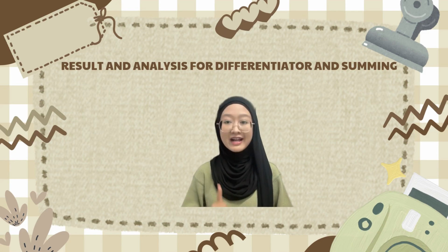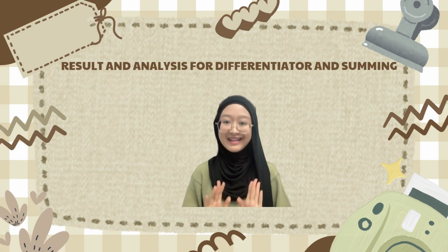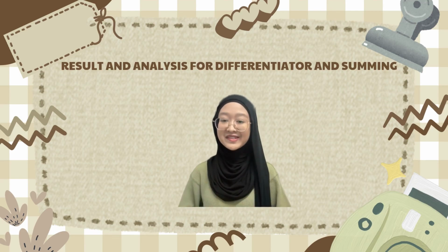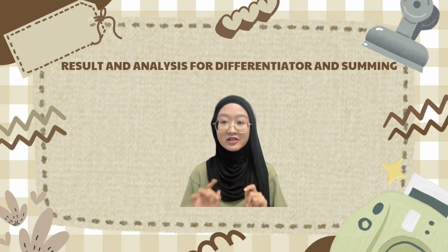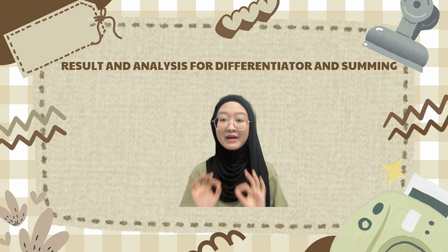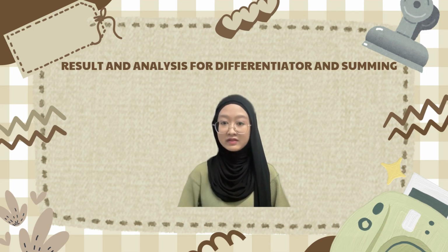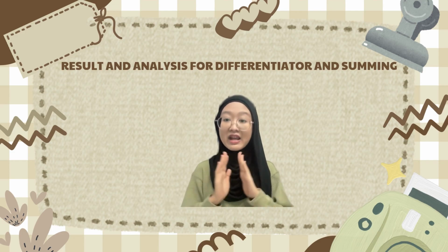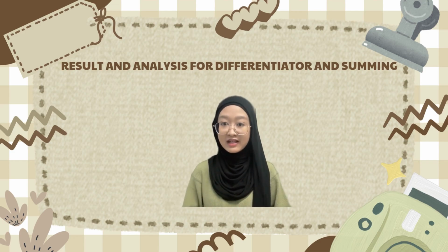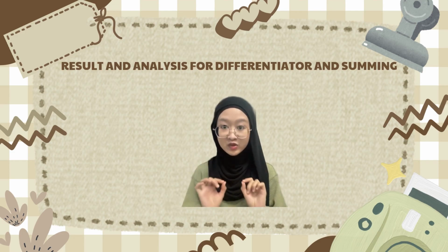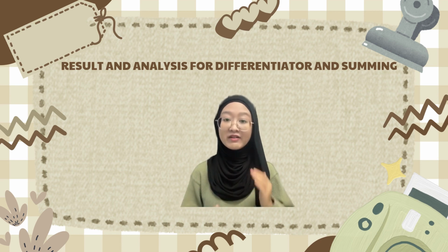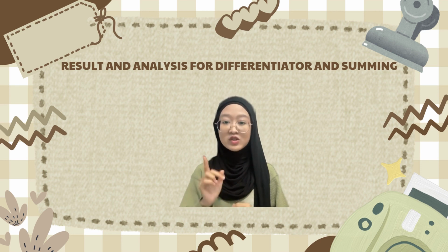For the differentiator, Vout is negative 1 volt for the theoretical part, while for the experiment Vout is negative 5 volt. At high frequency, a tiny 100 picofarad capacitor connected in parallel with the feedback resistor functions as a low-pass filter. By filtering out noise and avoiding the unlimited potential gain at high frequency, it restricts the high frequency gain, guaranteeing the circuit's stability and usefulness.